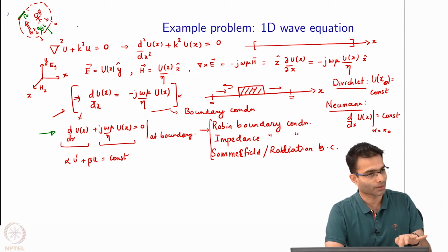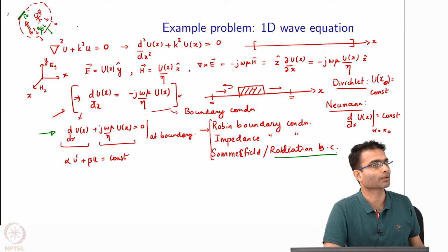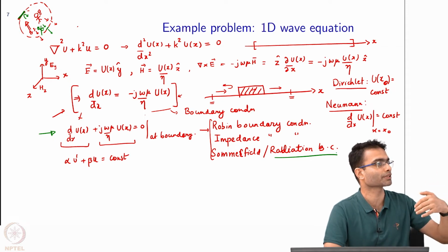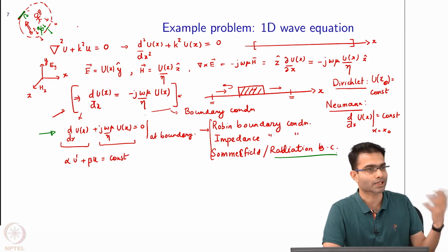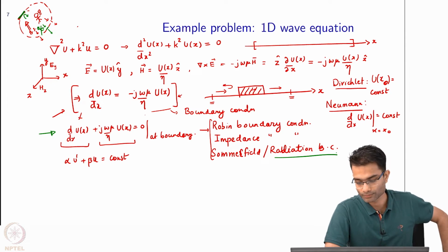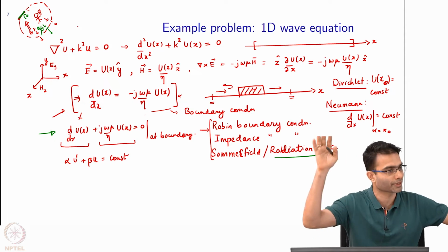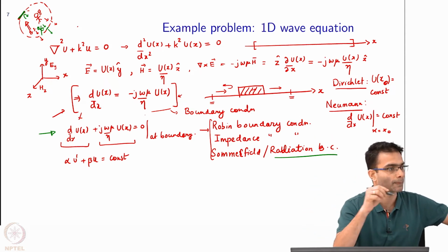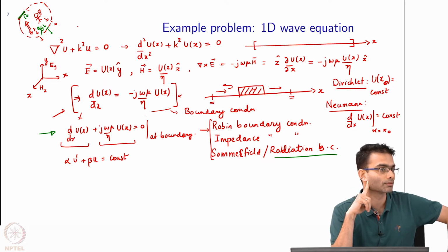So, that is why the name radiation boundary condition has come from the scattering people, because for them this is a radiation boundary condition, meaning it is simulating a radiation that is going off to infinity. Circuits people call it impedance boundary condition for different reasons, okay. But the physical interpretation is this: I do not want the field to come back from a hypothetical non-existent surface, okay. So, this is the motivation we will carry to 1D, 2D, 3D, however many dimensions we are solving the problem in.